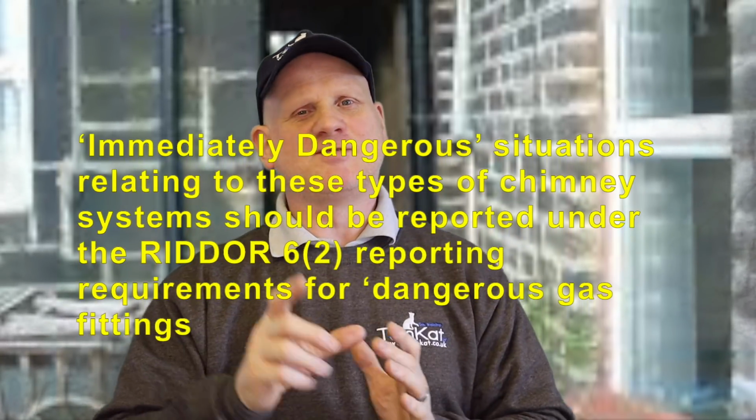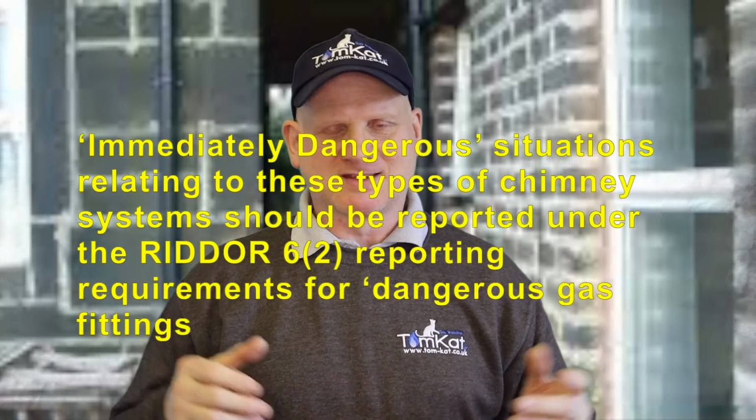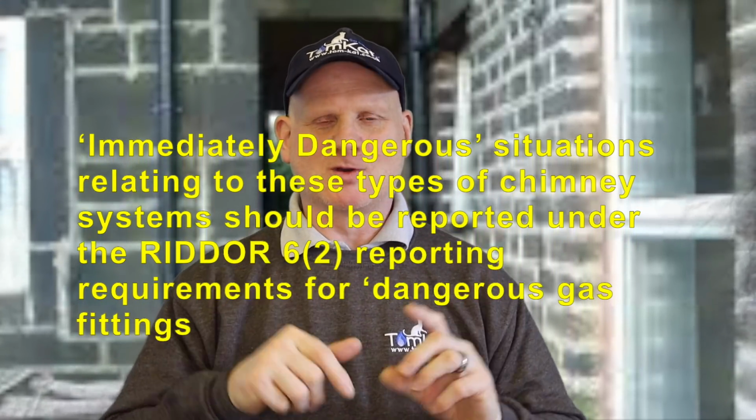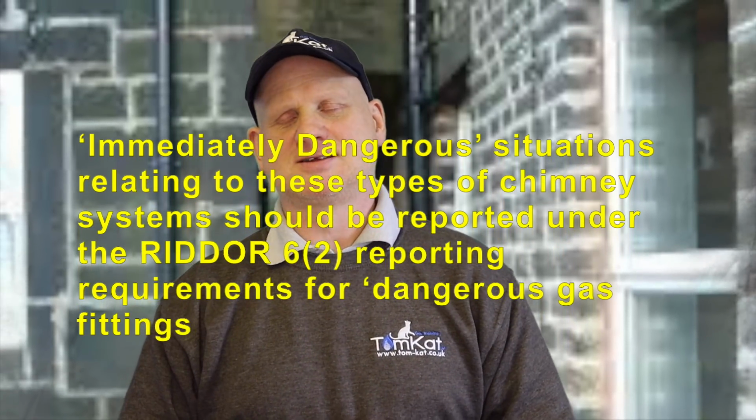Now, flues in covered passageways or ginnels. Now, GasSafe have produced a technical bulletin 007 for this to give you guidance on it, and you must pay particular attention to if there's bedrooms above the ginnel or passageway. My advice in this one would be steer well clear of it.